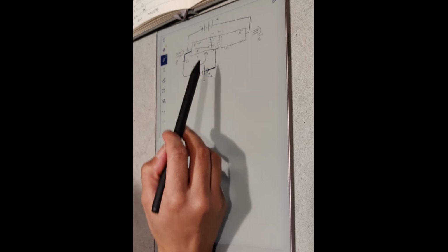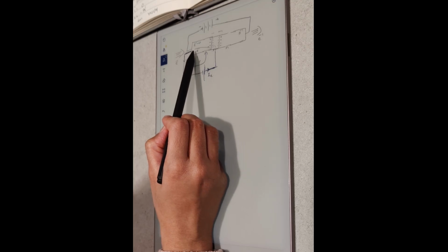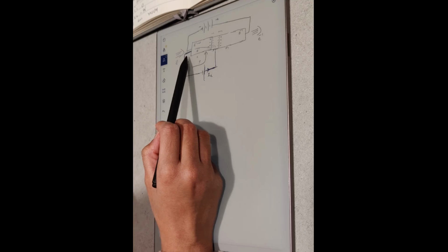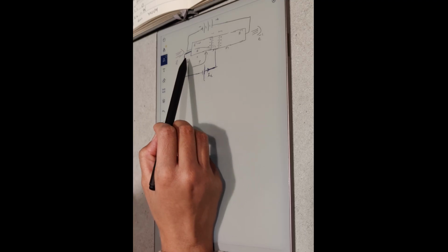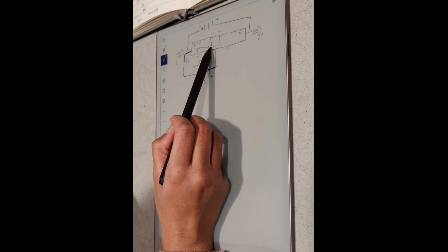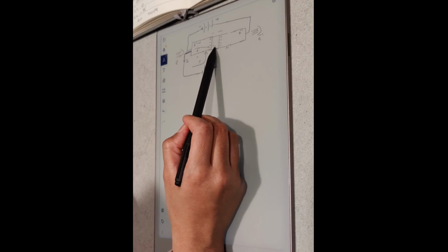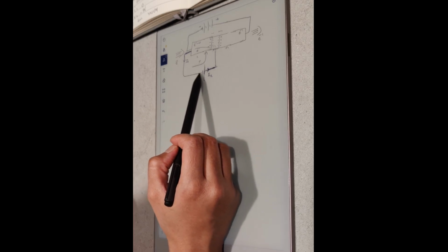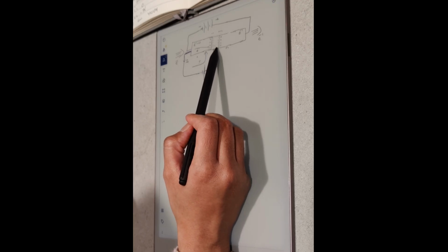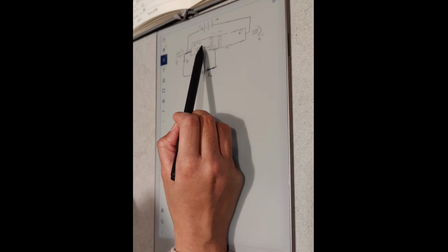So on this side, when I have mobilized the electrons, because I have now given this external battery which accelerates or excites these electrons, some of them are going to combine in the base, and then some of them are going to flow down to complete the circuit. But remember, this base is very thin, and this has a lot of free electrons.